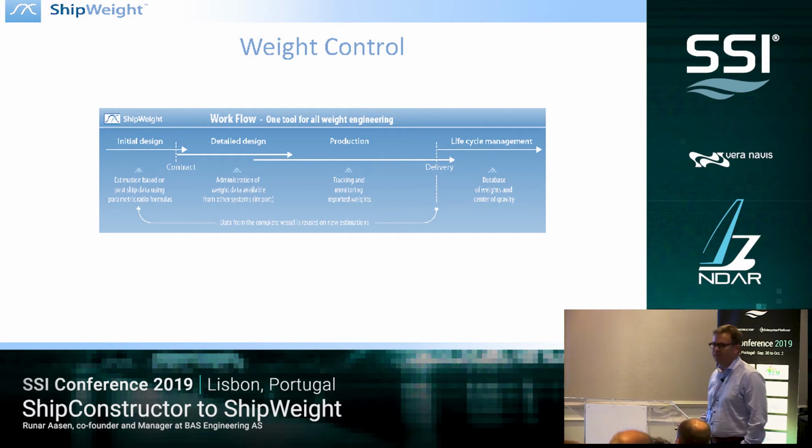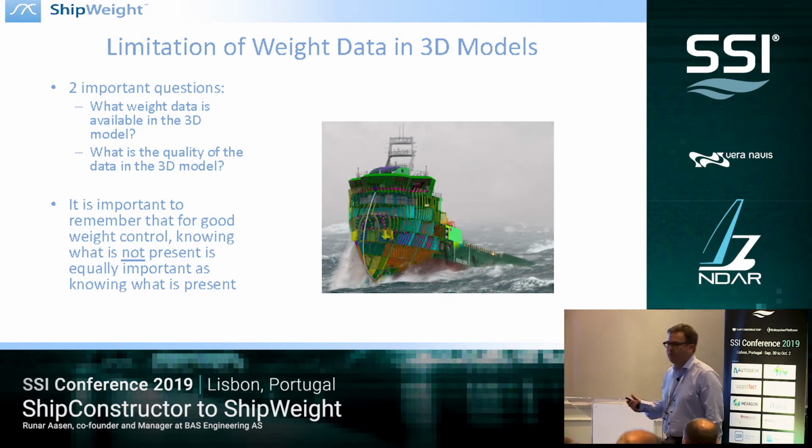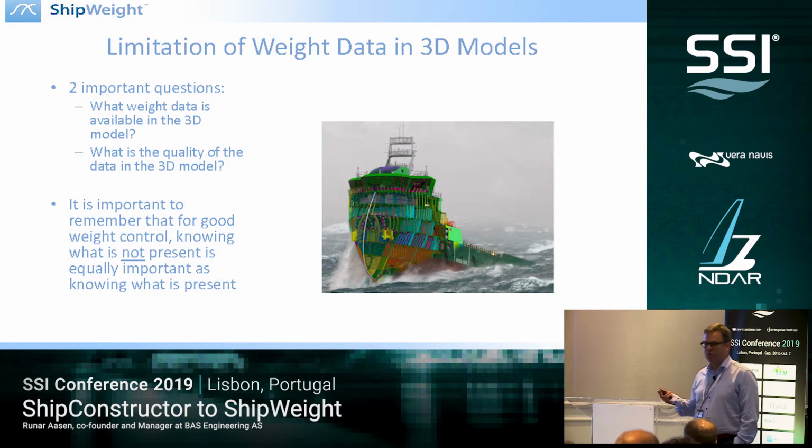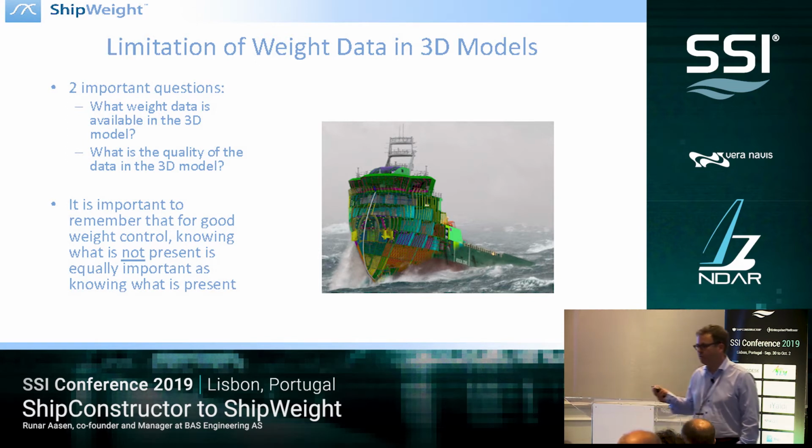Right, first thing, your CAD model is limited. There are some limitations of the weight data, and you need to ask yourself at least two questions. One, what weight data is available in the 3D model? And two, what is the quality of the data in the 3D model? The person who is drawing in the 3D model, is he thinking about weight at all?